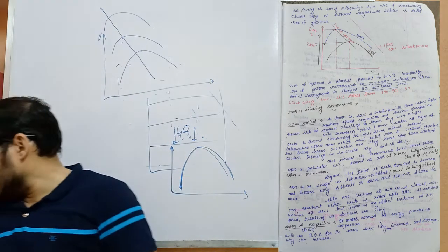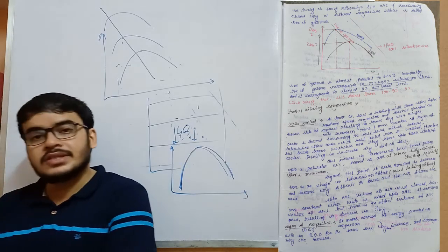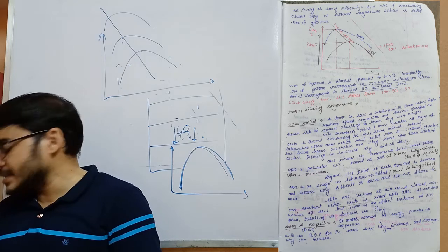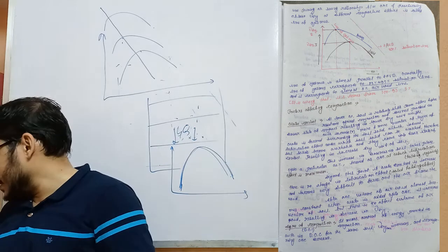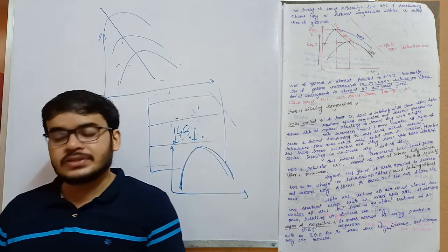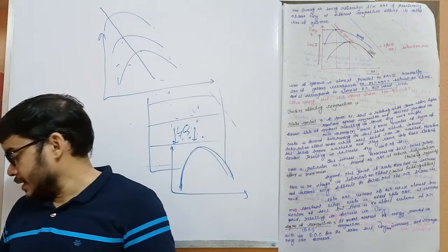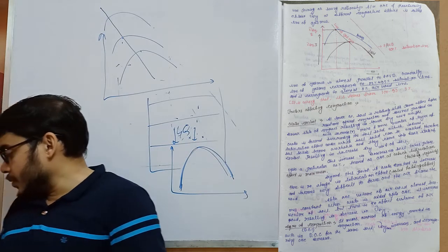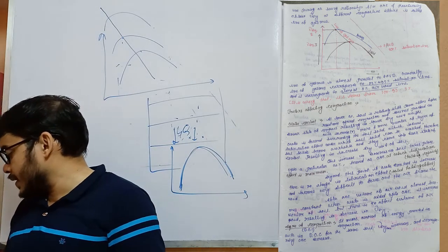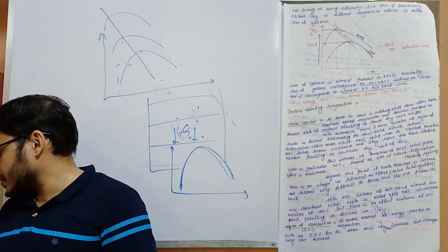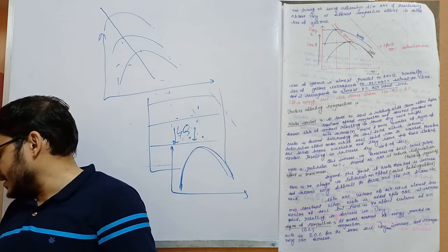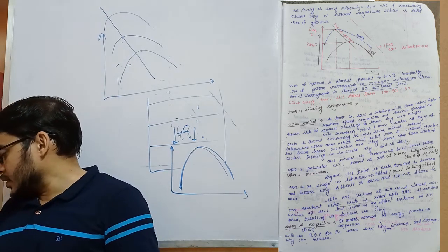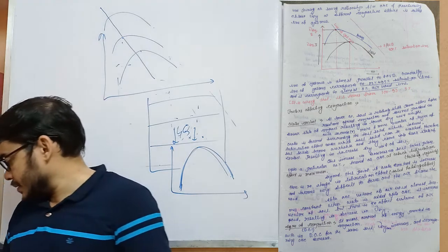At lower water content, soil is relatively stiff, hence offers higher resistance against compaction and does not pack into a denser state, resulting in lower dry unit weight. With increase in water content, more and more layers of water form surrounding the soil solids, which induces a lubrication effect under which soil solids can be worked.